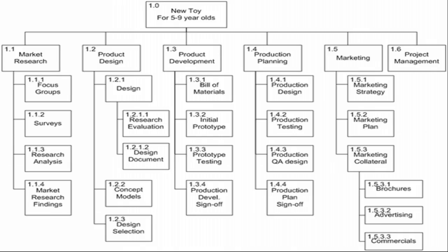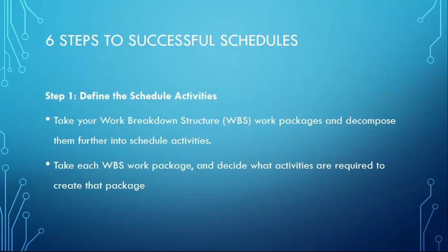Okay. For the work package, which is foundation, what activities do we need to do to deliver the foundation? Talk about clearing, deep pegging, excavation, laying of blocks and the rest of them. Those are the activities that are needed to deliver that work package. So what I have done is referred to as activity definition. So we're able to define the schedule activities.